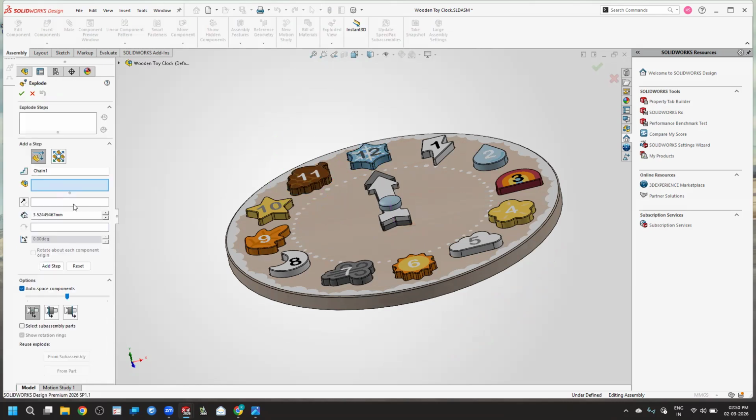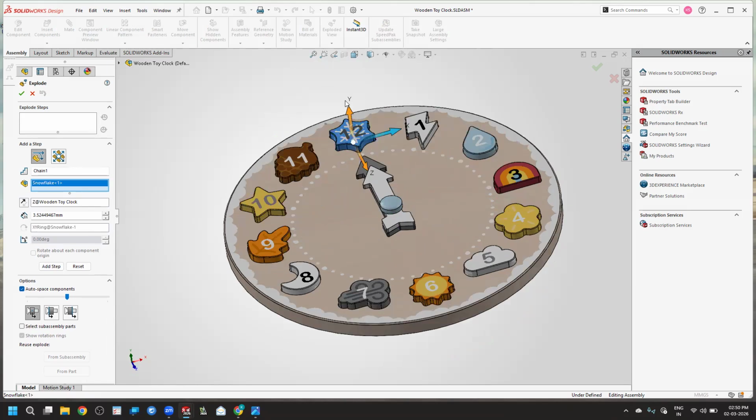First create the new exploded view and then choose which object you want to move. In this case, I'm selecting the 12th, and you can move it in the X, Y, and Z directions. Now I'm moving it in the Y direction, where you can see the scale beside the part you are moving. You can place it at whichever point you want, like at 40 mm or 50.